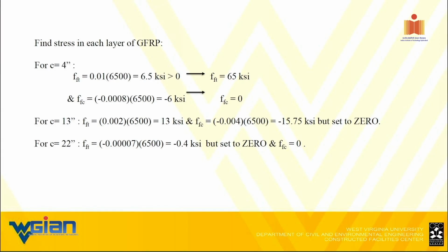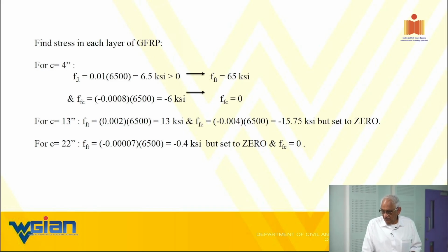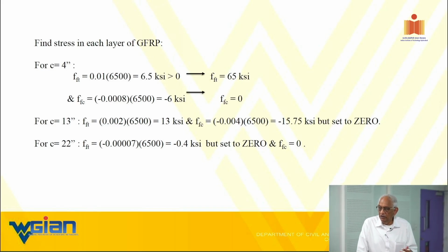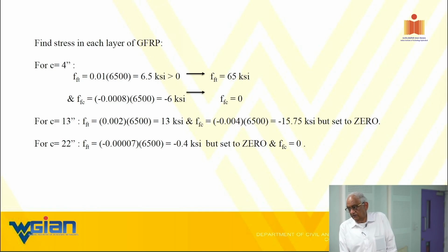This is not steel, this is a GFRP column. I'm just using that as an explanation for you. What happens when you go beyond 0.003 is still the same effect as if it is 0.003. And that is the explanation I'm giving you. But 0.003 is that of the concrete. Concrete will fail after that. Of course it fails after that.